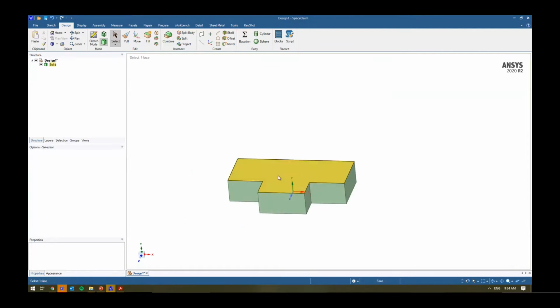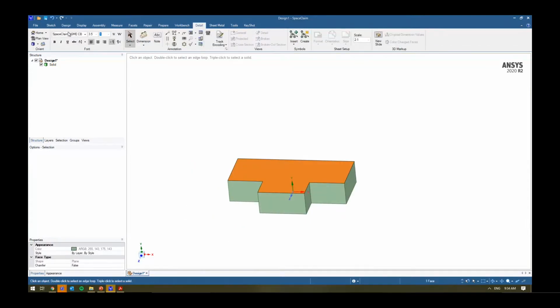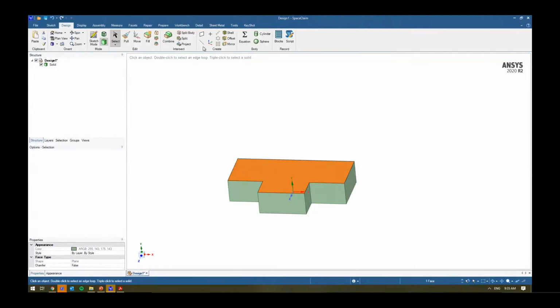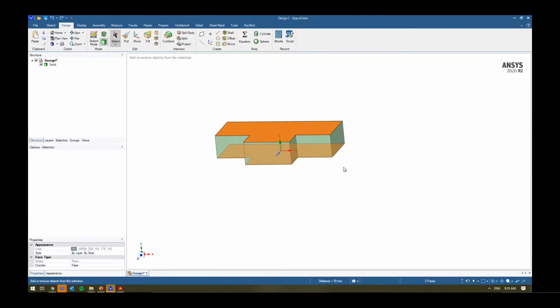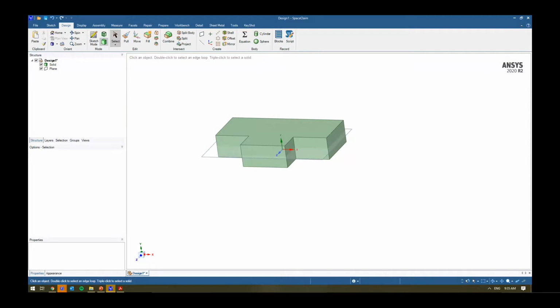So now what I can do is if I select something, I can use that. I can use my sketch, my design, sorry, to create a plane, right? If I delete that, I can select it, Control W, does exactly the same thing. If I select, say, two faces, Control W, it'll put a plane in the middle as well.